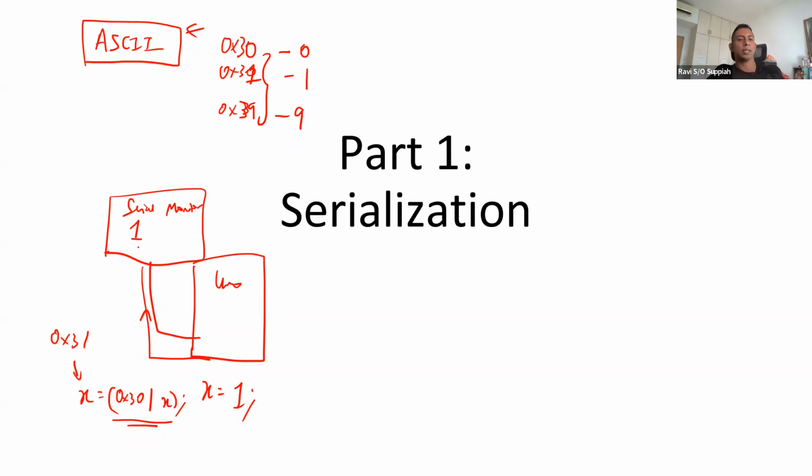Similarly, when I use the serial monitor to transmit data to the Uno, I'm also transmitting ASCII characters. If your Uno code is written to look for actual decimal numbers, let's say 1, 2, or 3, then like what you saw in the studio code, I need to take the data, which is the UDR0, and subtract the 0x30. When I subtract the 30, what is left is the last digit, which will represent the actual numerical value, not the ASCII value.